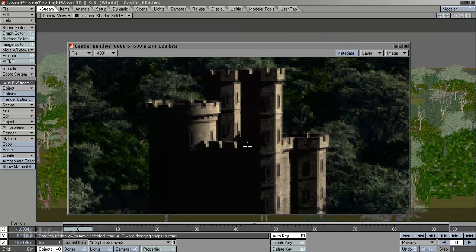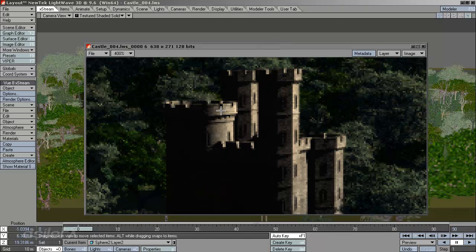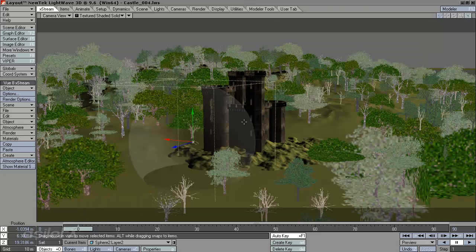So if we take a look close up into the render, seeing where the intersection is, which is basically right around this larger round tower, the coloration differences in diffusion between the objects is not just from the smoothing. It does differ. So that sort of anti-aliasing, and we can see where the intersection is moving along the side, it does clearly change the look of the object. So that is one thing to keep in mind, that anti-aliasing through that transparent object may look different, and also the overall render output could look different.